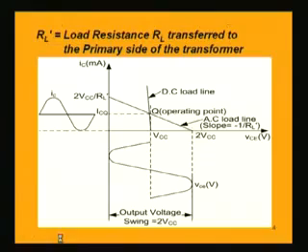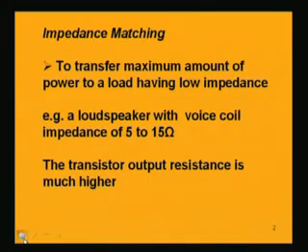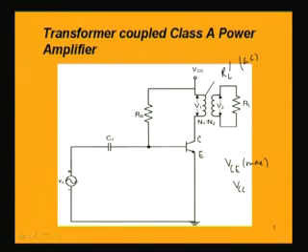the load line, if we want to draw it for AC, then when there is no signal, the voltage from collector to emitter will be simply VCC, that is the DC source VCC. Now, when you apply this signal Vs, which is a sinusoidal voltage, the current in the collector will be sinusoidally increasing and decreasing. It will be a sinusoidal wave.